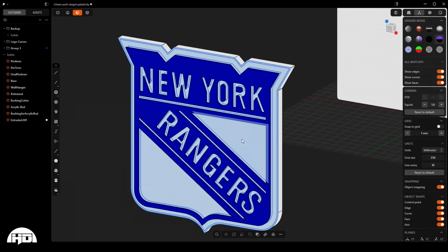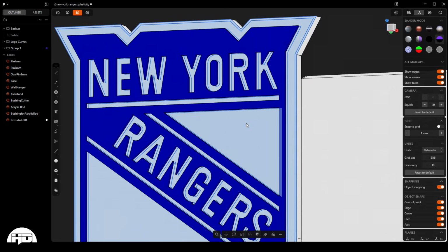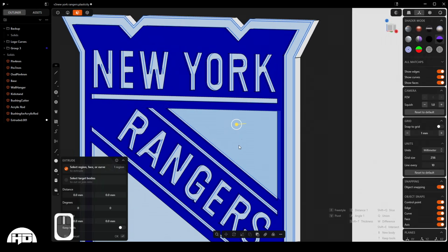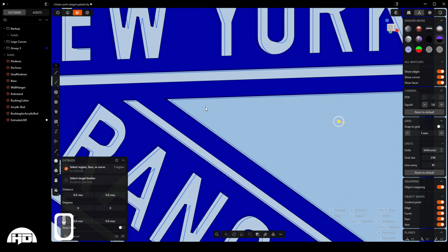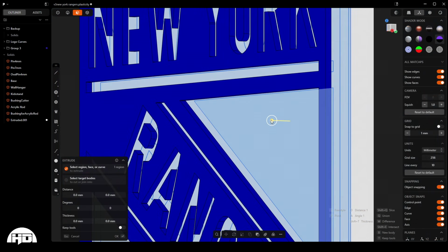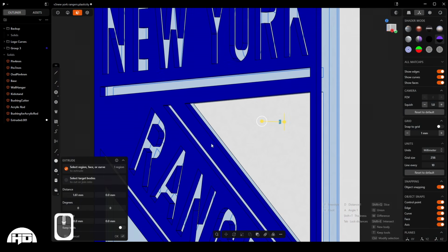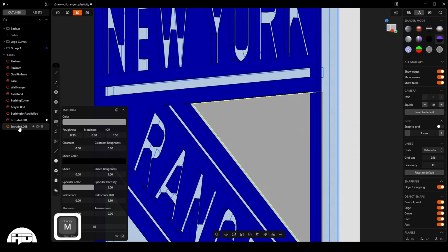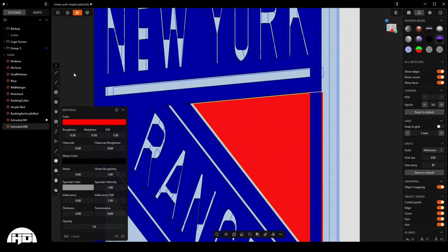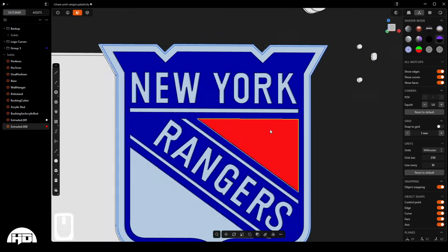All right, and this is the last one that we need to do, which is just the red triangle. Now, you can see basically what I will do is I'll bring that out, we'll extrude that, and we'll do 2 millimeters. Okay, right click. I'm not going to group that because it's just one body, but we'll select M for material, color, go to red. Right click to commit.